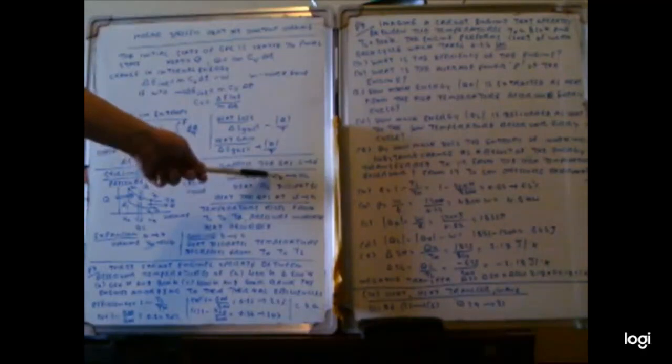Now, based on the Stirling engine. Here is the Stirling engine. First, the gas is compressed from C to D, from the initial volume VB to the final volume VA, so VB is greater than VA. When the gas is compressed, heat QL is dissipated. And then heat is added from D to A.